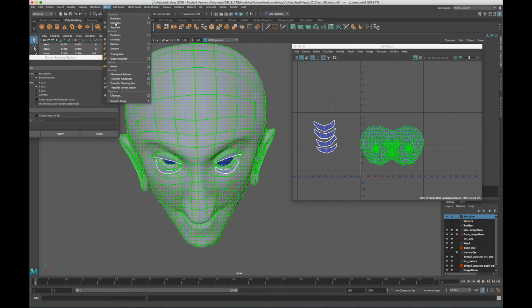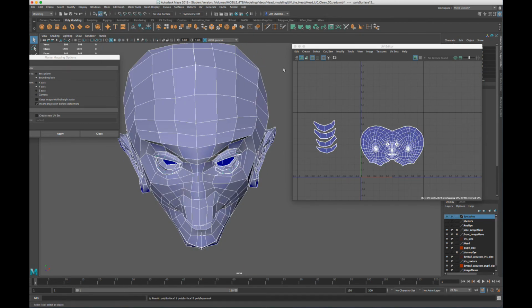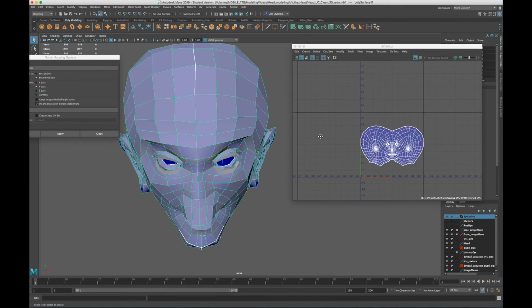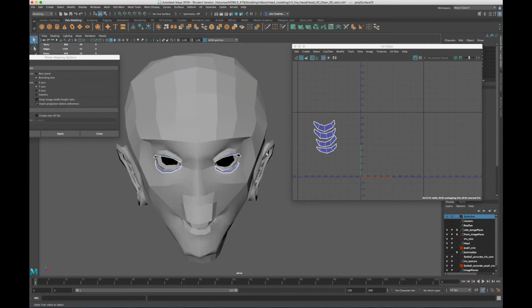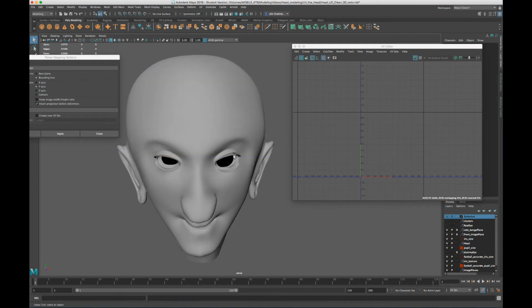I'm going to go back up into mesh and separate. Now I have the separate meshes back, and when I look at it, only that's on there. I can hit 3 to smooth them, and they're back and separate. So combining and separating just puts them into the same mathematical space. It doesn't fuse them permanently together, and that's really nice, because you're going to need to know that if you ever take rigging and you want the head separate to make facial expressions and shape animations, yet you want it combined as one mesh for the texture.